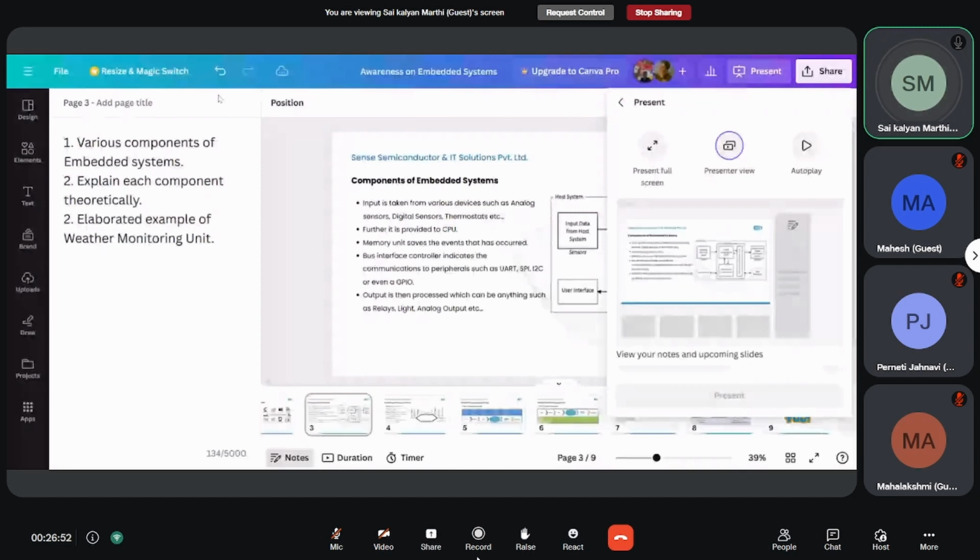Then the hardware team is going to do the feasibility and market study and BOM optimizations. BOM is nothing but bill of materials, and feasibility and market study are like what are the fast moving components which are there in the market. Not all the sensors available in the market we can procure. There will be a particular sensor which has all the 3 components in one single go, but that is not a fast moving thing. We have some other sensors, 3 different sensors, but they are very fast moving and available all the time.